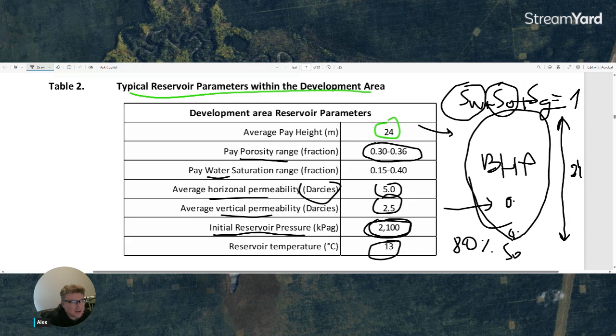And it's really a function of the vapor pressure curve and the bottom hole pressure injection, right? So bottom hole pressure, temperature, the volume in the chamber, and maintaining the chamber pressure and the reduced viscosity of the bitumen. This is one of the issues with this technology. It's energy intensive, and that's why NCG co-injection reduces the energy intensity, because by definition you don't inject as much steam.